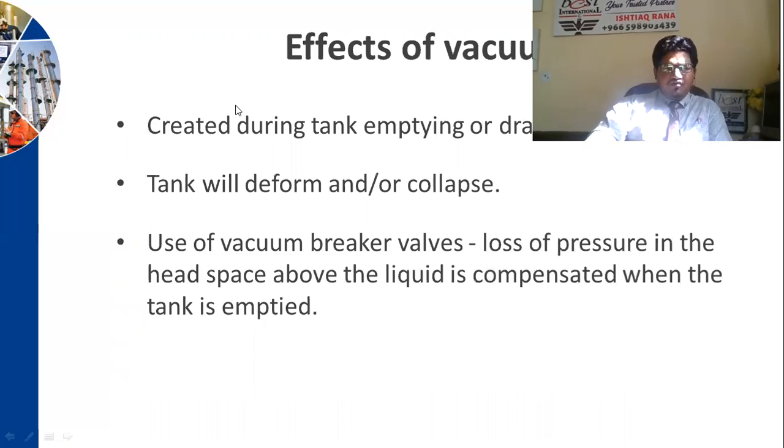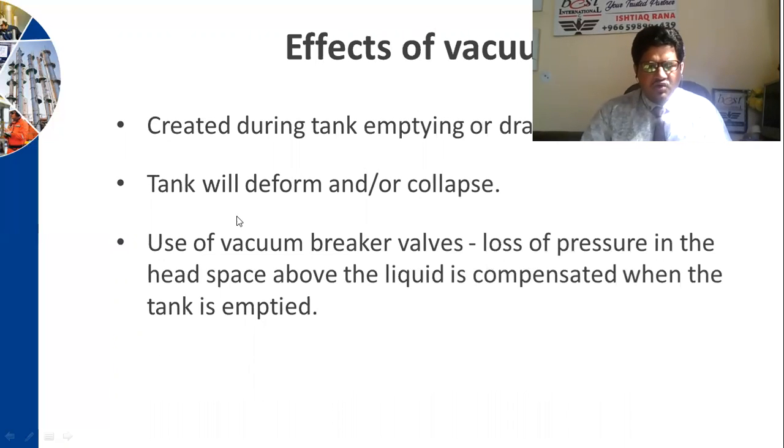Now, effects of vacuum created during tank draining: the tank will deform or collapse, so use vacuum breaker valves, as loss of pressure in the head space above the liquid is compensated when the tank is empty.